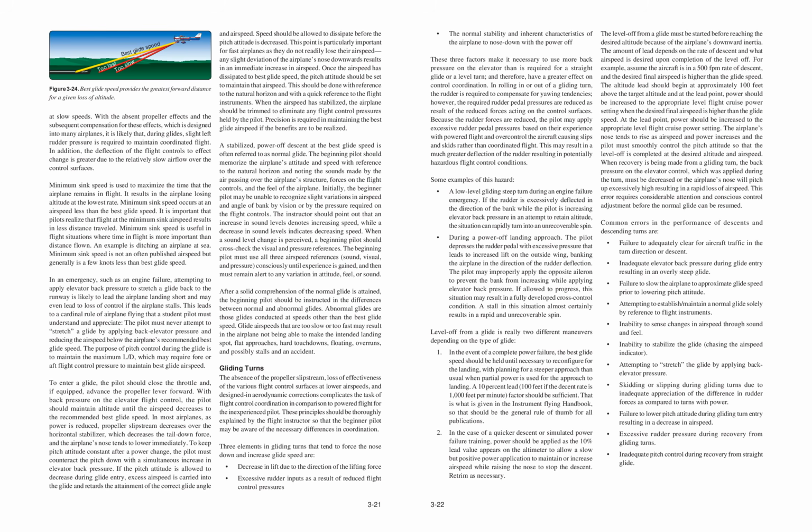Minimum sink speed is useful in flight situations where time in flight is more important than distance flown. An example is ditching an airplane at sea. Minimum sink speed is not an often published airspeed but generally is a few knots less than best glide speed. In an emergency, such as an engine failure, attempting to apply elevator back pressure to stretch a glide back to